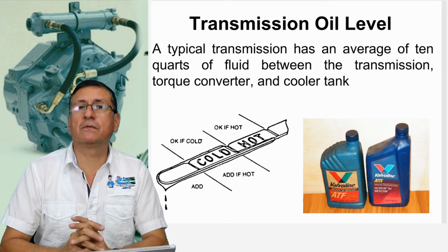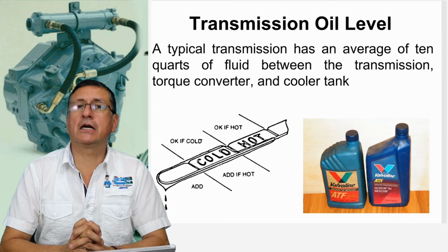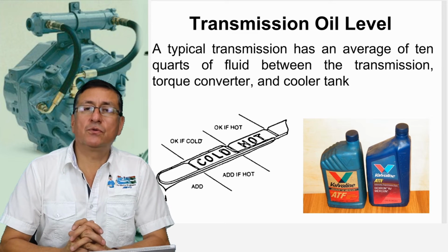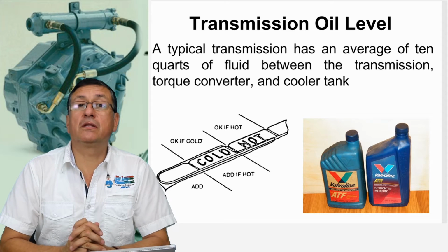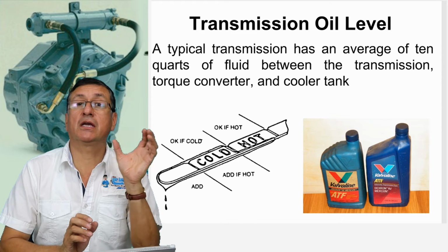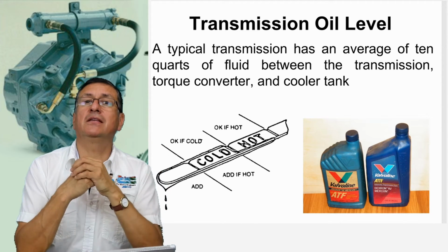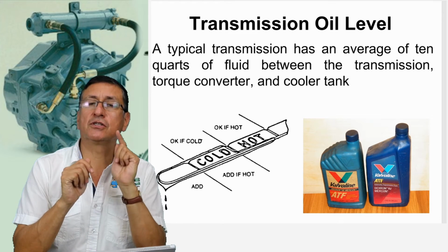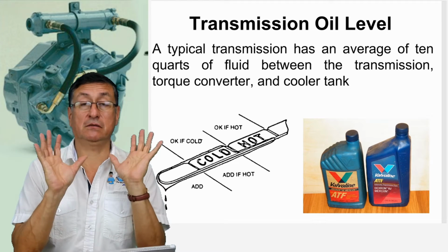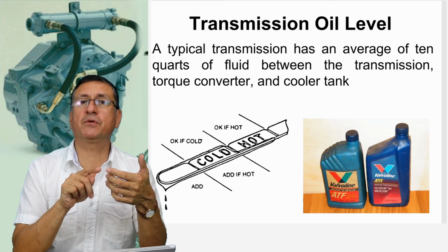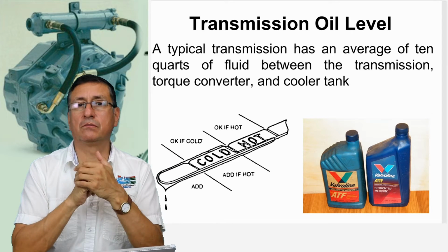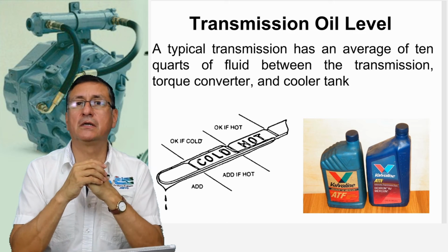Be careful, because automatic transmissions are very sensitive with respect to the quality of the oil. You will find oils that, if you check the gallon on the back, say exclusive for European transmissions, for Volkswagen and Nissan. This one is for European transmissions, exclusive for BMW, exclusive for Mercedes-Benz.